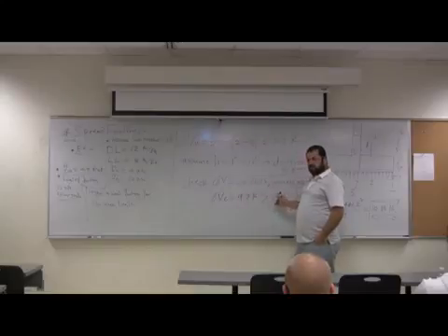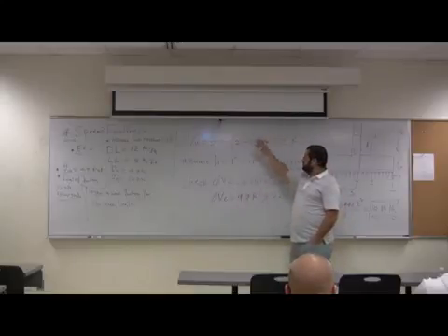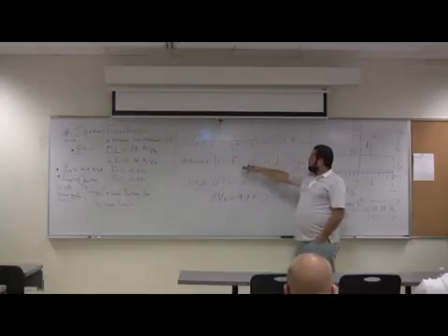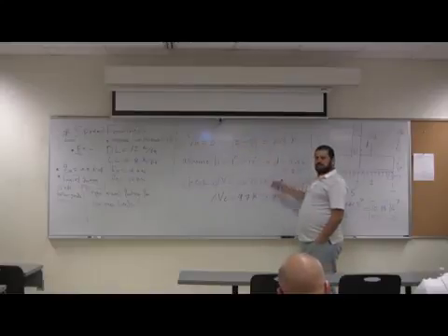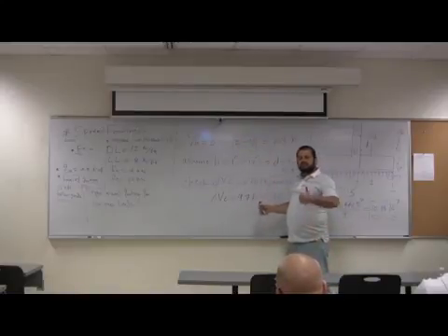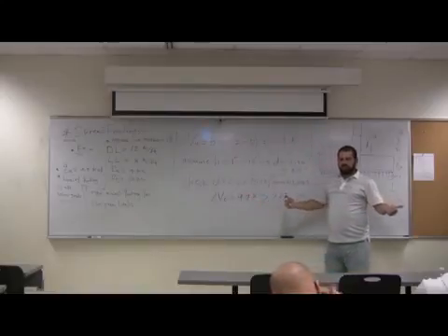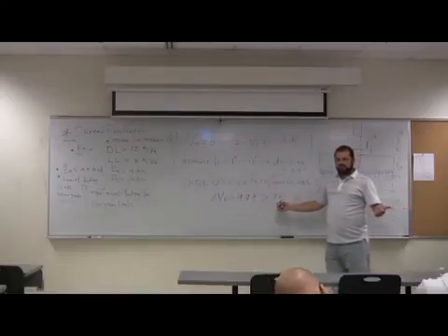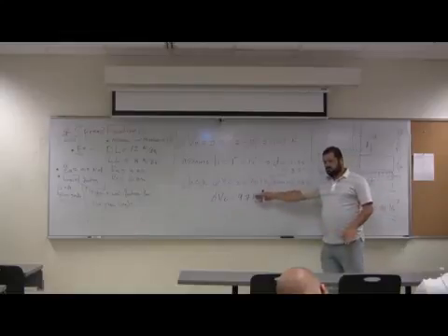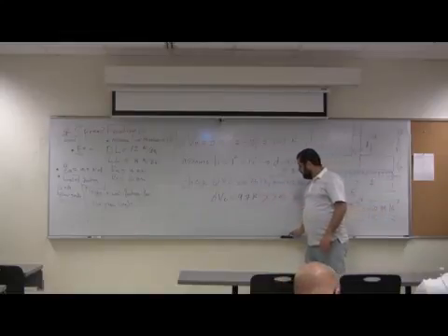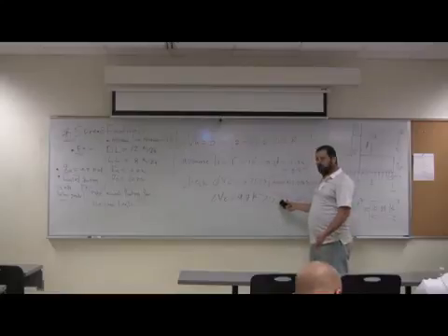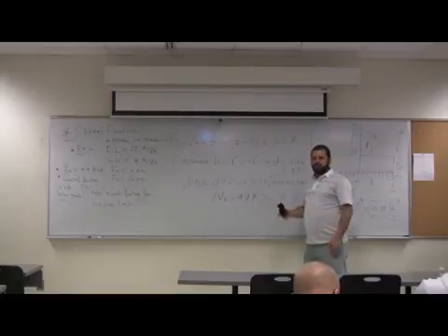So now we're good. Let's assume someone will say, you know what, I'm going to use 10 inch and decrease this one. That's fine, but remember, increasing D will save you some steel, right? Increasing D will give you more strength in moment, so it will save you some steel. This is good.